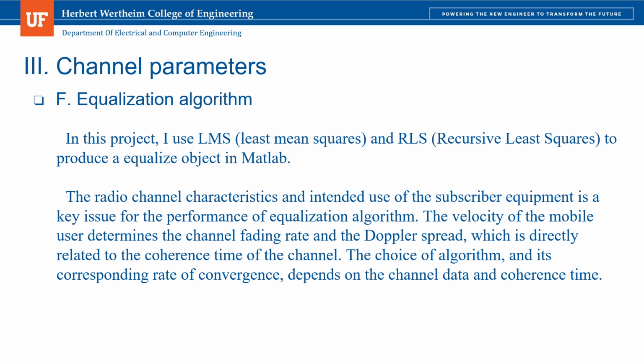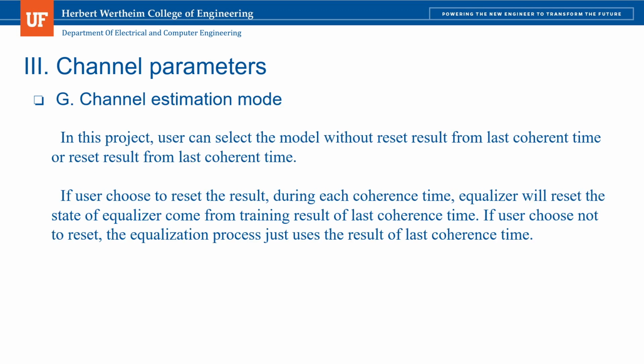And about the equalization algorithm, in this project, I use LMS and RLS to produce an equalizer object in the Matlab program. The radio channel characteristics and the intended use of the subscriber equipment is a key issue for the performance of the equalization algorithm. The velocity of the mobile user determines the channel fading rate and the Doppler spread, which is directly related to the coherence time of the channel. The choice of the algorithm and its corresponding rate of convergence depends on the channel data and coherence time.